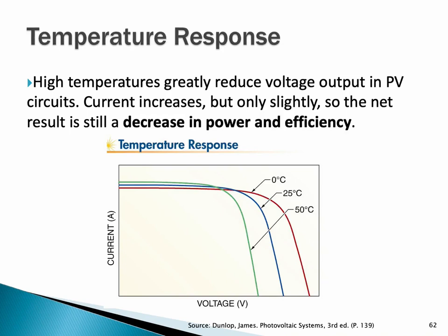When I raise the temperature to 50 degrees C, my voltage is going to go down significantly. As I decrease temperature, voltage is going to increase significantly. That's what we're going to work on next week. We're going to run through temperature coefficient calculations to determine the maximum voltage and the minimum voltage of a module or an array. And we're going to make strings.